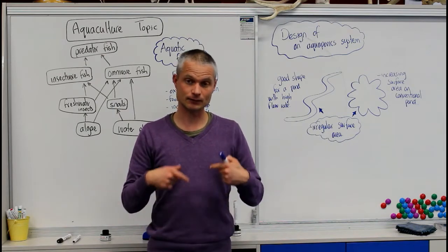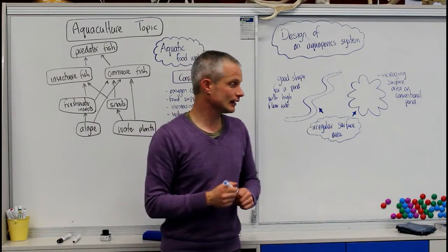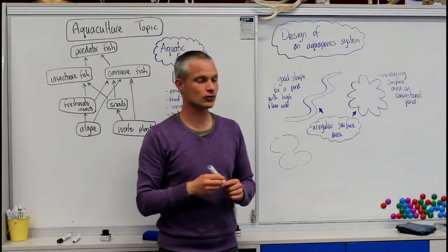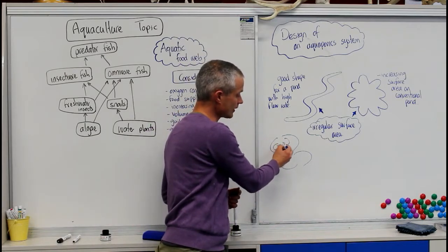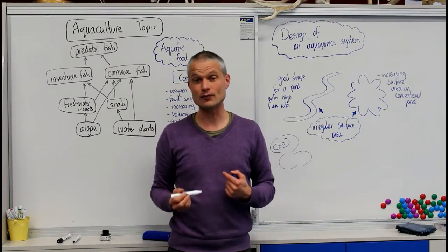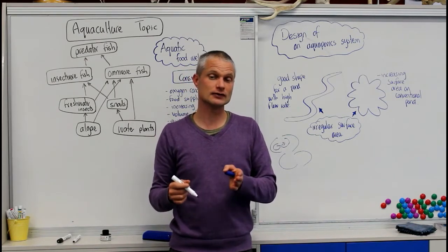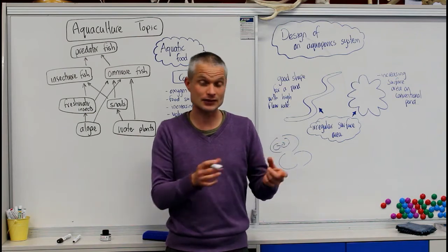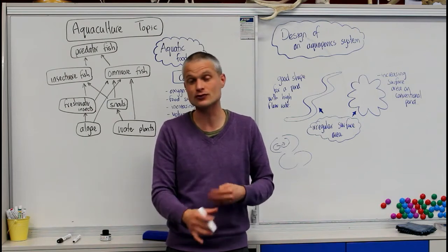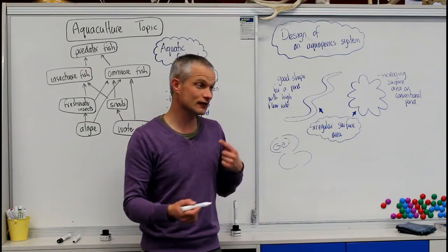You can incorporate that pumping of water in with a filtering mechanism too, so you can pump it through a water circulation system, so that as the water circulates through that, it's going to be oxygenated before it hits back into the pond again. Or it could go through a gravel bed that has reeds growing in it, and as it goes through the gravel, it's going to get oxygenated, but also purified by the bacteria living on those stones, but also the biological action of the reeds and the microbiology associated with the roots of the reeds will cleanse the excess nutrients out of that water before it goes back into that pond again. Or you can even integrate the two.